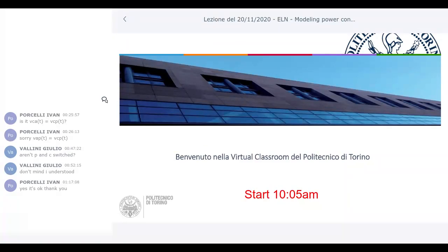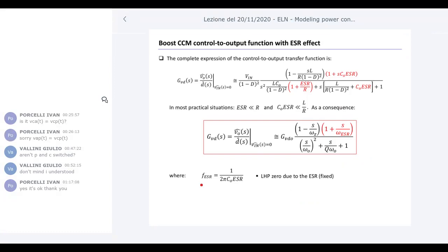What can we say about the state space average technique? In analyzing the system, you may understand that this technique always works, provided that you correctly analyze and write down the state variable equations for all your reactive elements for each of the time intervals in which the structure is not variable.